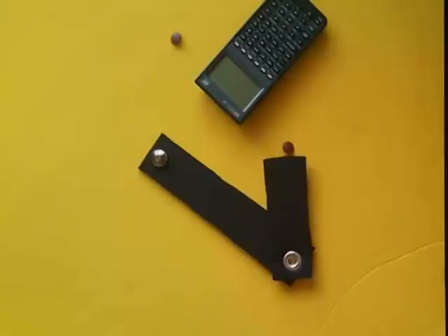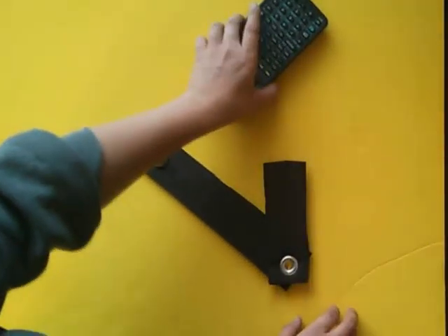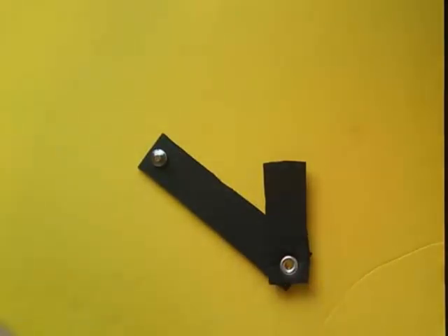So the first thing I'm going to do is draw the configuration space. In this case, my configuration space has only 2 dimensions because I have only 2 joints, theta 1 and theta 2. I'll now check what is the range of motion that each of these joints can go through. When I check the workspace of my manipulator, I ignore for the moment my start and end points, and I ignore any obstacles in the space.